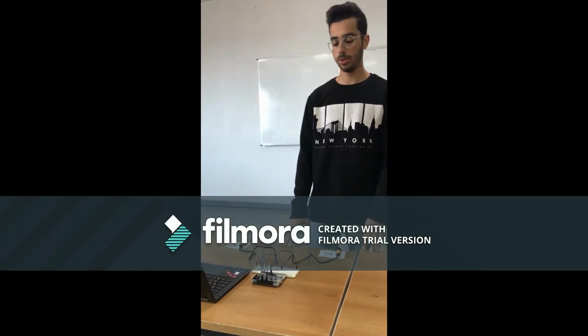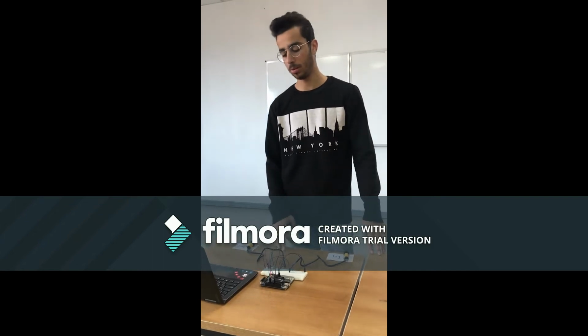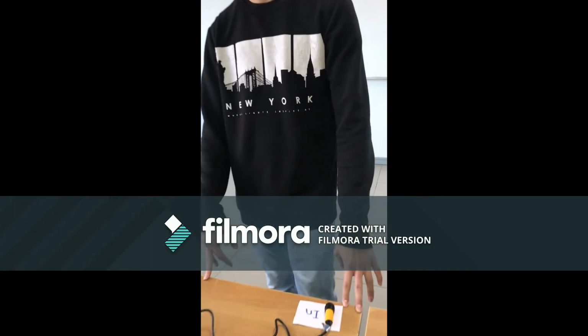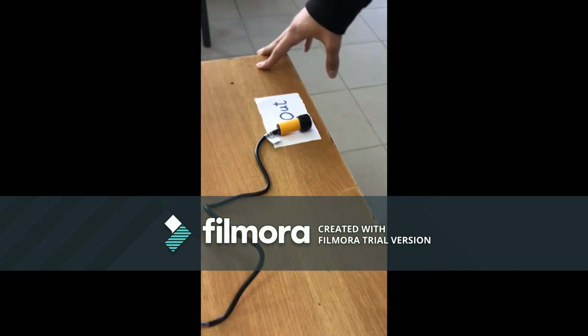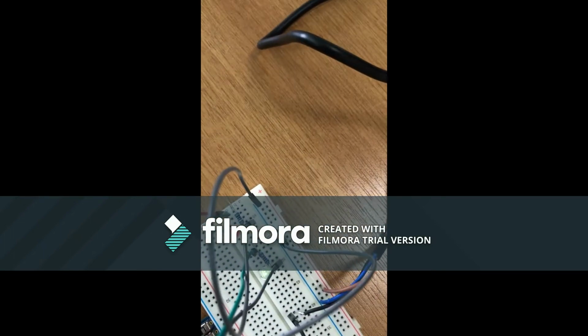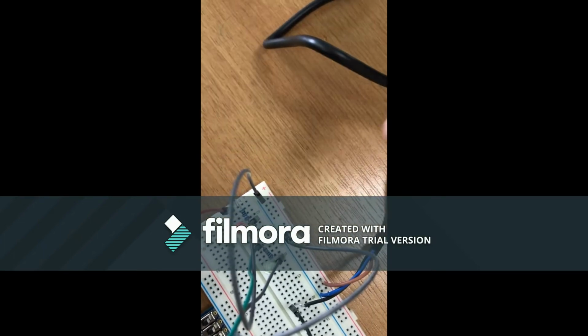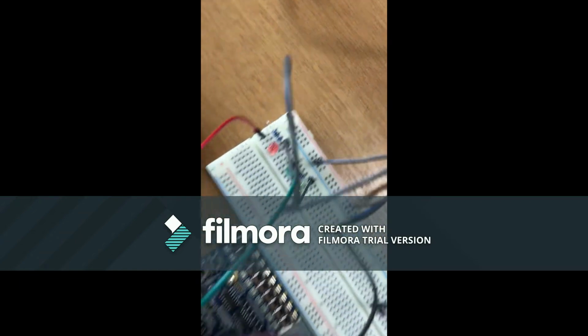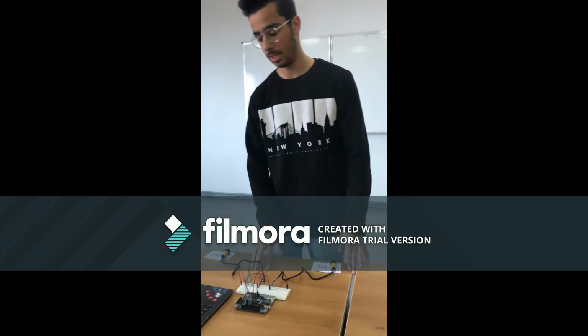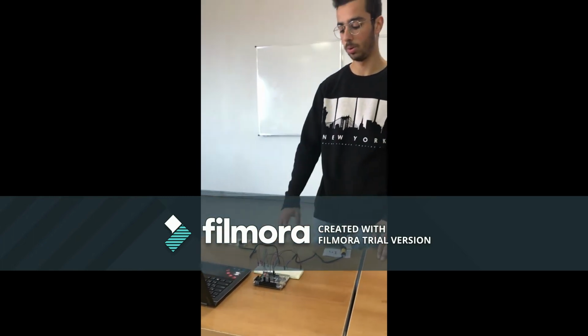I'll introduce you to the hardware we used in our project and the components we used. We used two proximity infrared sensors, one for the entrance to the lecture hall and one to get out from the lecture hall. And we used two LEDs, a green one and a red one. The green one indicates whether the door is closed or open. If the red one is lighted, then the door is closed and no one can enter the hall.